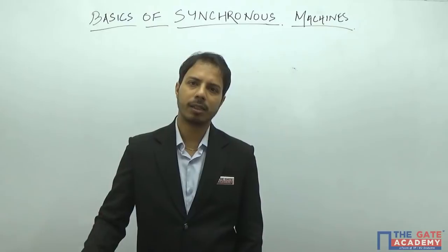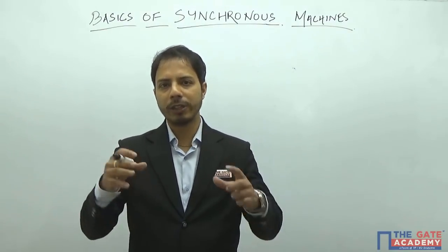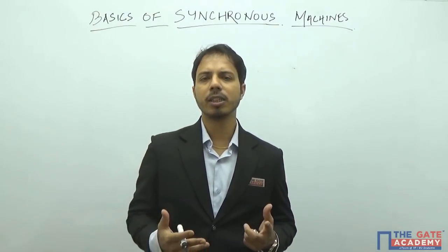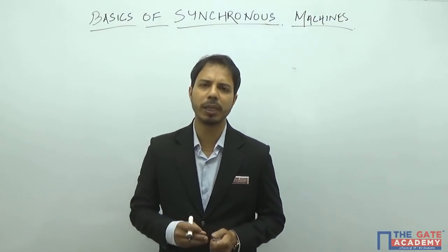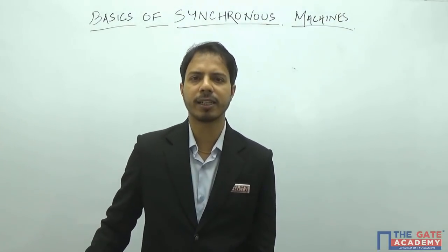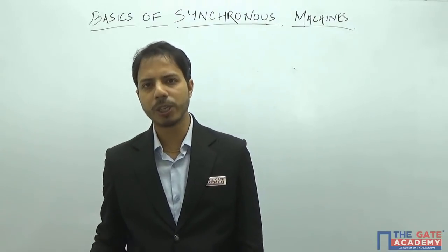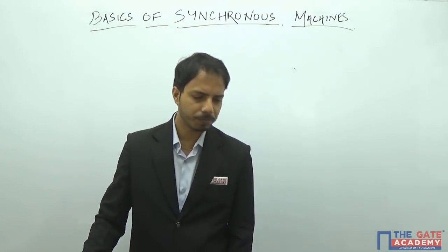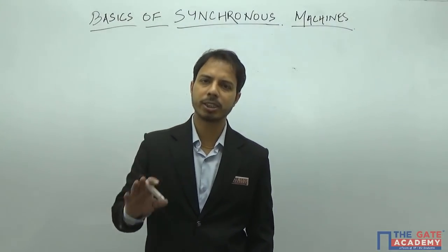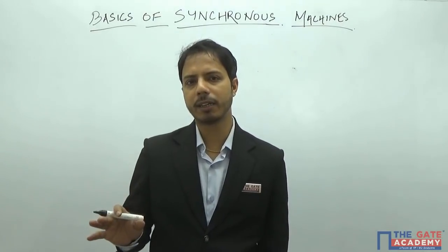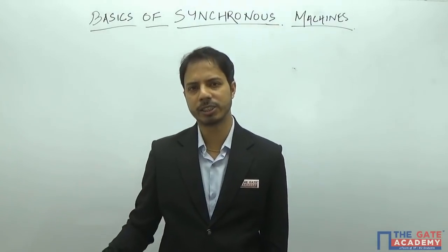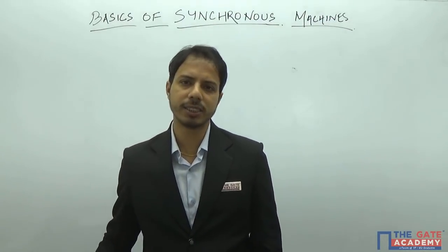Basically, we give these windings in the stator. Whenever we have three-phase windings and we give a three-phase supply to that winding, we will have a rotating magnetic field, which I have explained in the earlier videos. So please refer to them if you have difficulty understanding the concept or the visualization of the rotating magnetic field. Now, the rotating magnetic field is present in the induction motor also. So the stator is basically the same for synchronous machines and induction machines. The actual difference is the rotor.